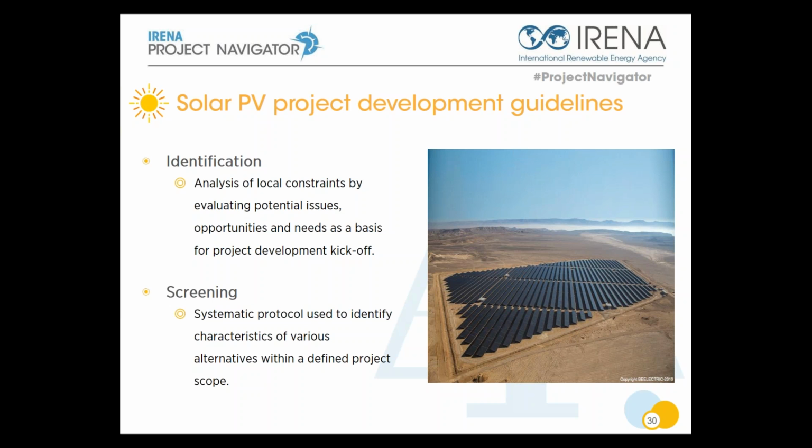One aspect that is also very important in order to identify an opportunity for solar PV is what kind of configuration my site will provide. For example, it's important to consider the horizontality and the level of your terrain and understand what criteria will define the successful implementation of a solar PV field.